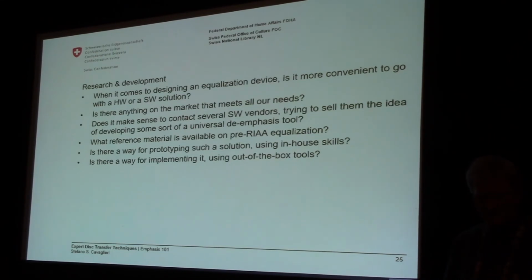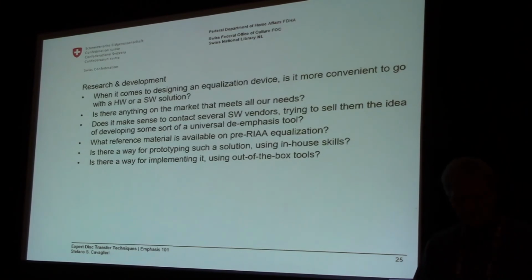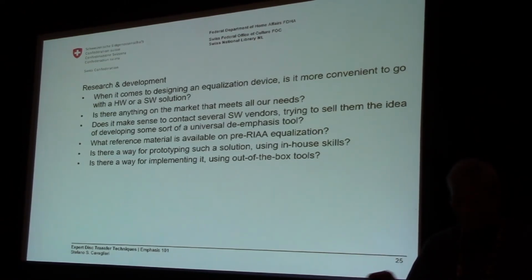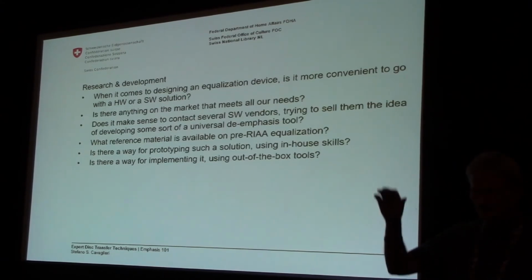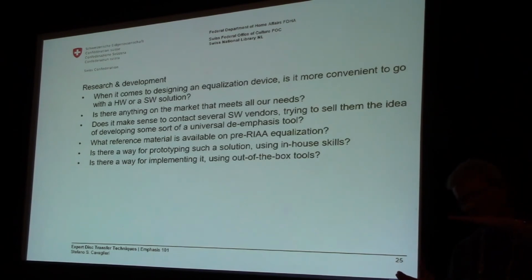So we also asked ourselves whether there is or there is not a way to prototype such a solution using in-house skills. I'm lucky enough to have sound engineers working in my department as well as IT guys. So we have developed a little tool that does all the calculations, at least, for any combination. Velocity, amplitude, with pre-emphasis, without pre-emphasis, with a 6 dB slope or a 3 dB slope, whatever you can think of.